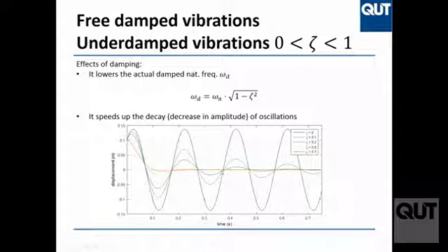Okay? Clear? The frequency omega d is affected by it, because look at how this is one period, and when I increase the number, this moves a bit further on, making the period a bit bigger, which means the frequency is a bit lower, but not much. As I said, the effect on the frequency is very tiny. So omega d changes, but not so much.